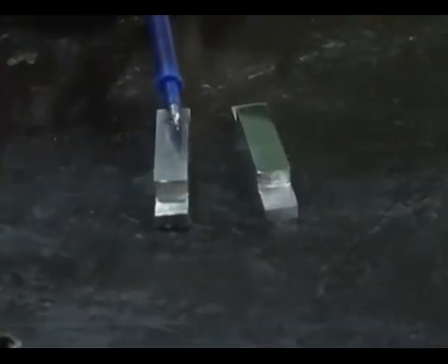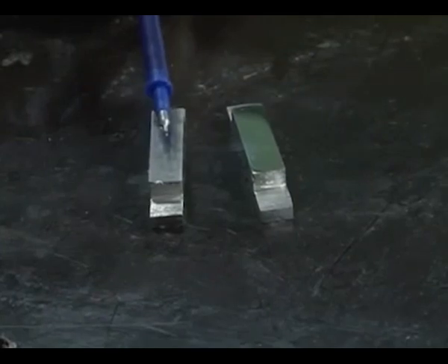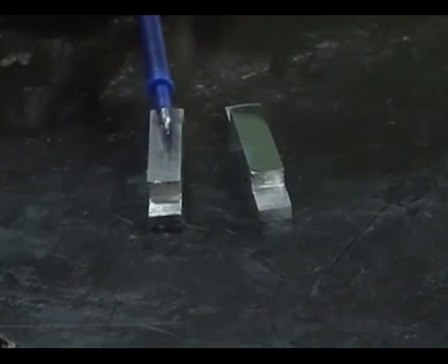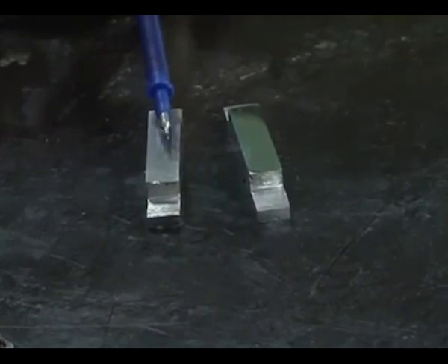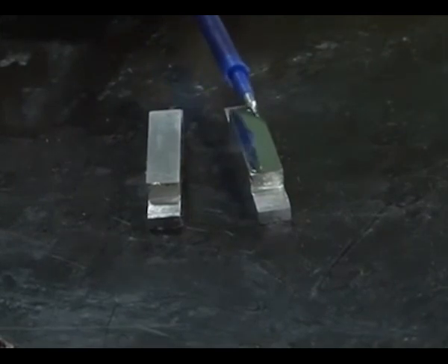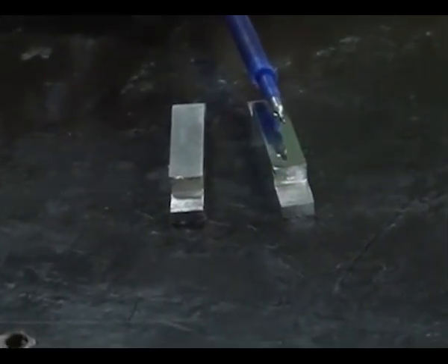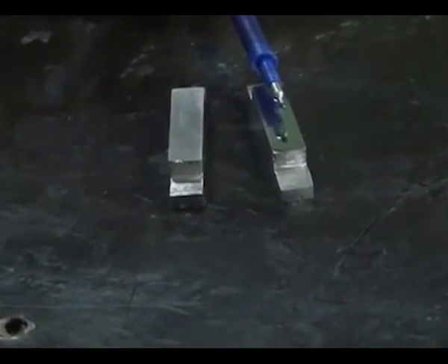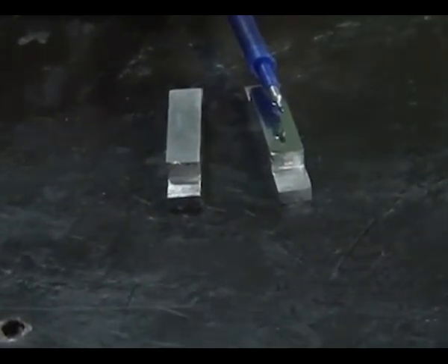This is the initial workpiece made of stainless steel, wherein the image of the refill tip as well as the refill blue portion is not visible perfectly. After finishing with the rotational abrasive flow finishing process, you can see the image of the refill as well as its tip. This clear visibility shows the finishing ability of the rotational abrasive flow finishing process.